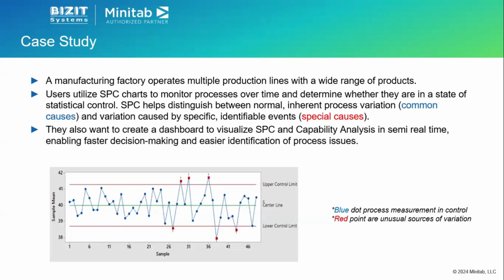So how to use the control chart? First, we put your process measurements in time order. For example, I measure the dimensions. So every 2 hours, we collect the dimension reading from the process.